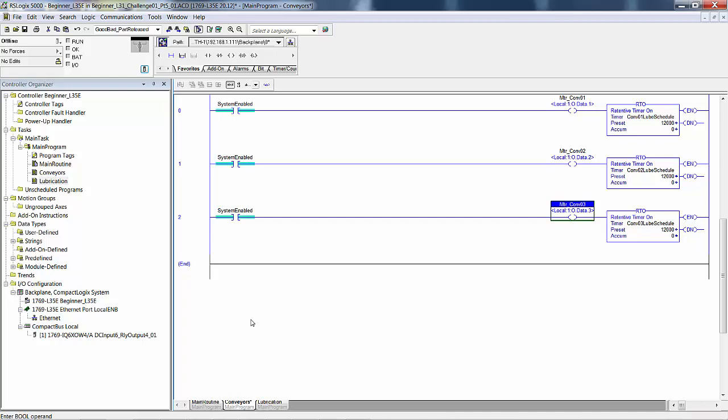We want to use these conveyors as a part feed buffer into our manufacturing system. That means that we want to put parts onto Conveyor 1, one at a time. Have the conveyor run just long enough to pull the part all the way onto the entrance space of the conveyor and then stop and wait for the next part, filling up the conveyor with parts one at a time until it is full. If you didn't shut the conveyor off, once the part got onto the entrance, it would just run all the way to the end. We want it to stop as soon as it's all the way on the conveyor.